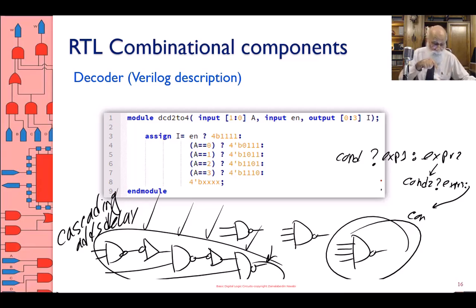I'm going to show you the example here for the 2-to-4 decoder. Assign I, the 4-bit I. Something new I'm showing you here is vector declaration. I've shown you A and B declaration for the AND gates. Now I'm showing you vector declaration. In Verilog, when you declare vectors, it goes into square brackets. When you declare your inputs and you want 2-bit inputs, you say input [1:0]. That gives you 1 as the leftmost, 0 as the rightmost.